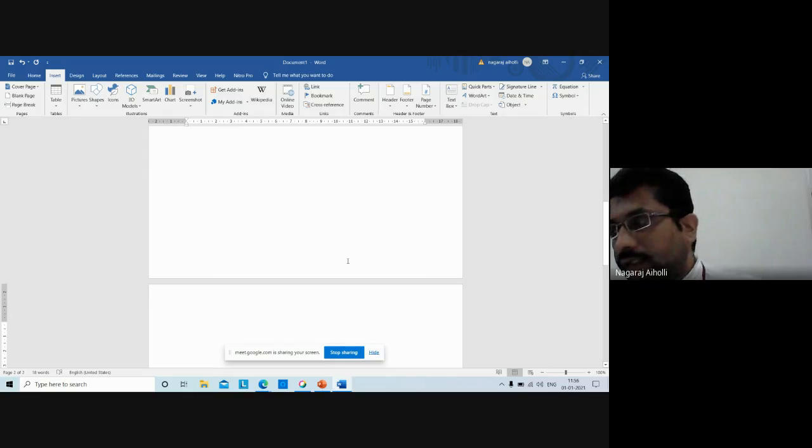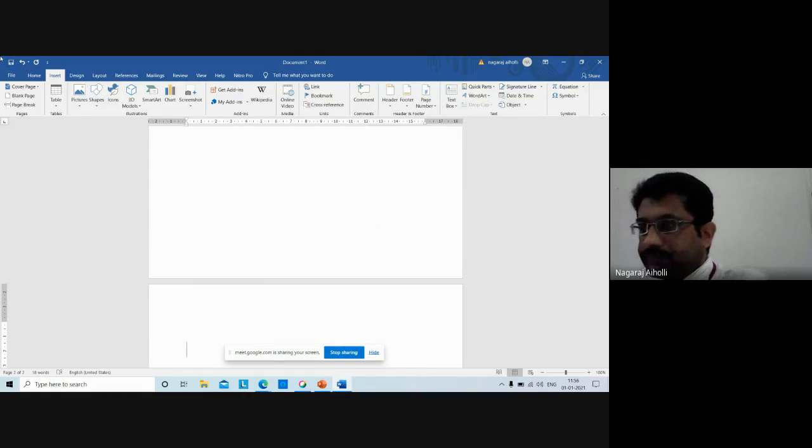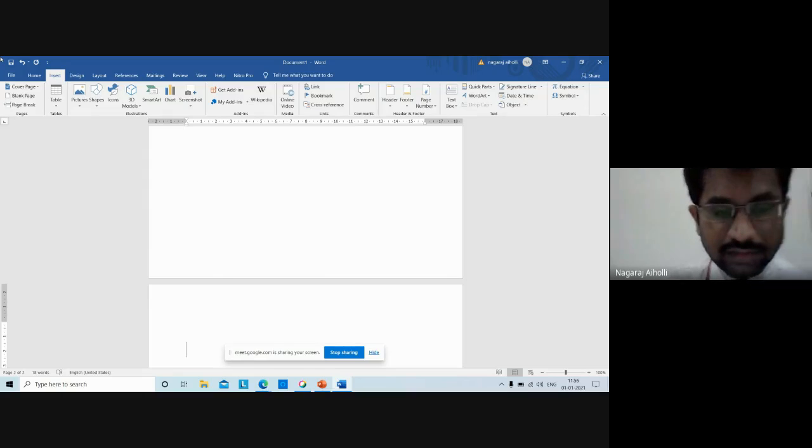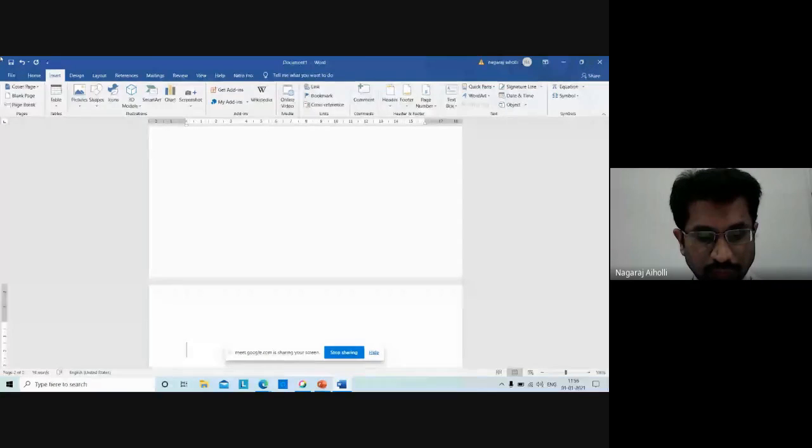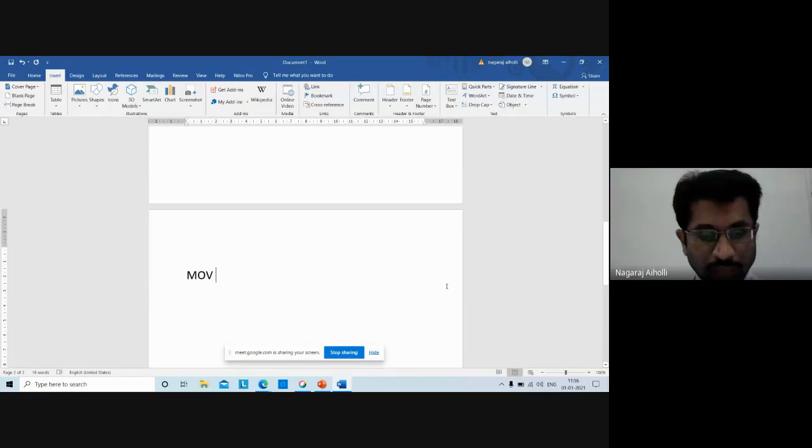So the program will be... which mode are we studying now? We are studying timer in mode 1. So we have to make use of the TMOD register: MOV TMOD, #GATE C/T bar M1 M0. Gate, C/T bar, M1, M0 is the 8-bit structure of the TMOD register.